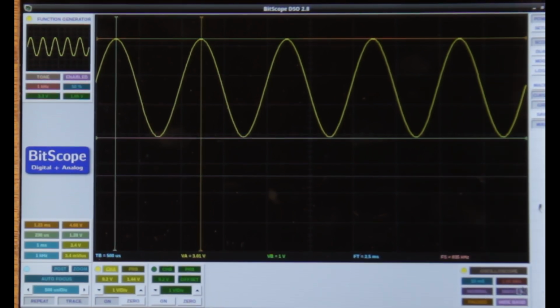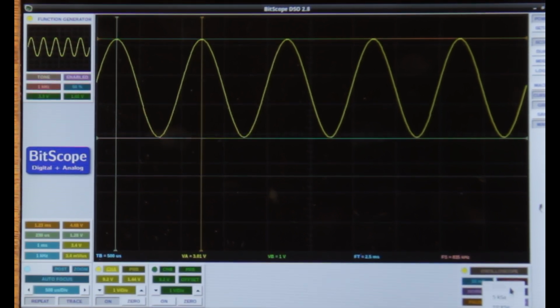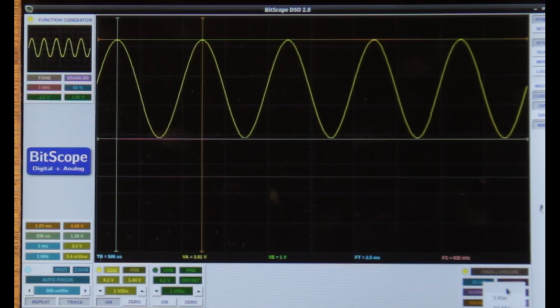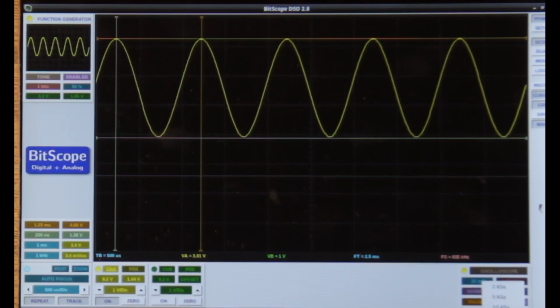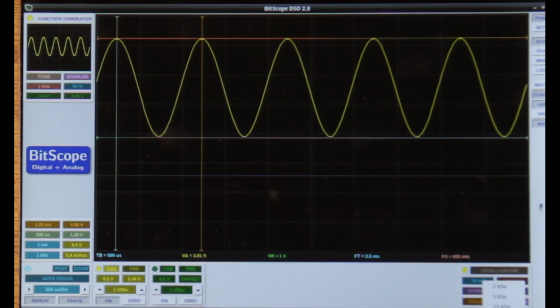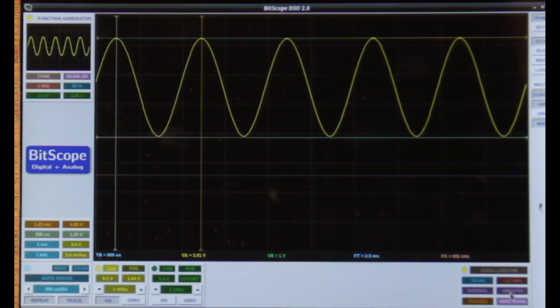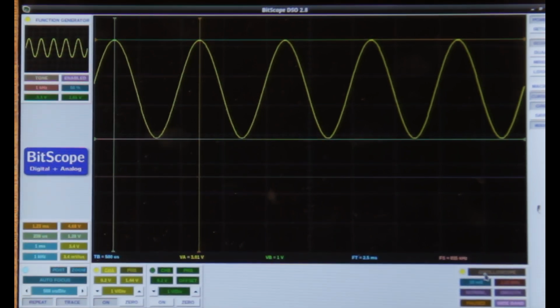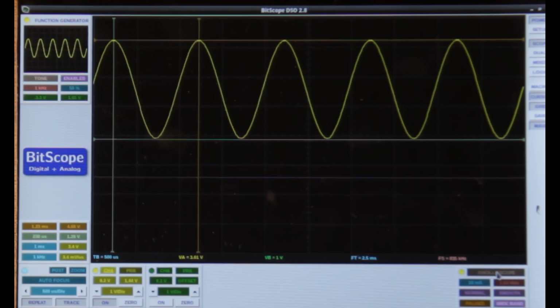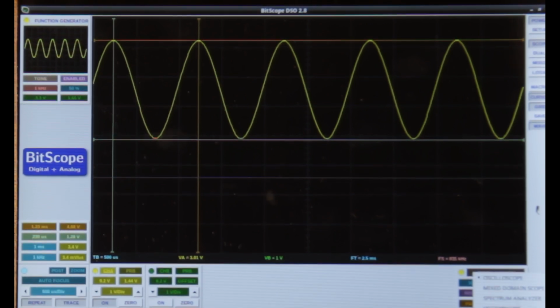It allows you to change the number of samples that it saves from 2 kilosamples down to 12 kilosamples, so 12,000 samples. So that's what's stored in the display that you can then scroll around. It also allows you to do some things like have either sharp or smooth, so there's some smoothing. And it also allows you to change the oscilloscope from an oscilloscope only into a mixed domain scope, a spectrum analyzer, a phase analyzer, or a Vectorscope.